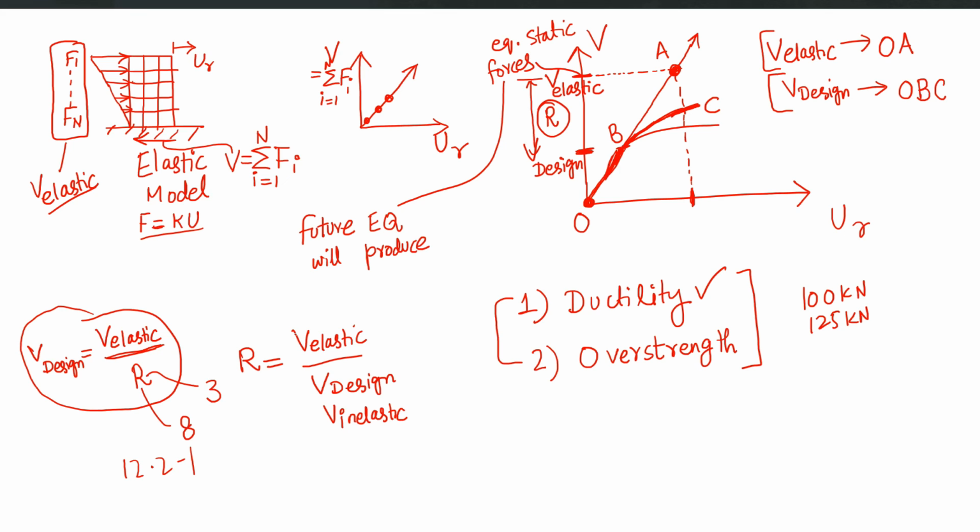But if you perform nonlinear time history analysis and your model is nonlinear, then there is no need of these code based seismic design parameters, no need of R factor, because whatever capacity is in your structure, the model will be able to follow that line. It will not essentially be following a straight line as the elastic model will do, right?